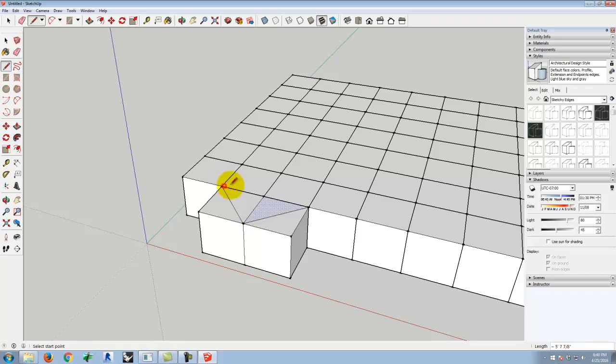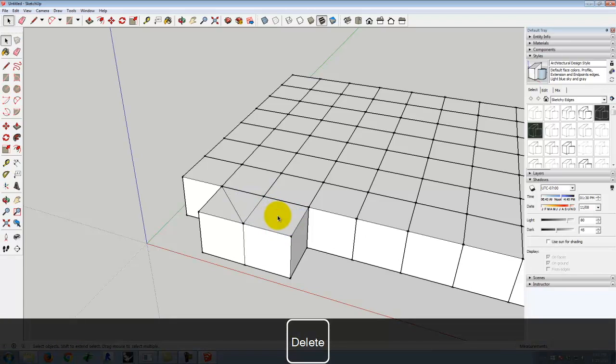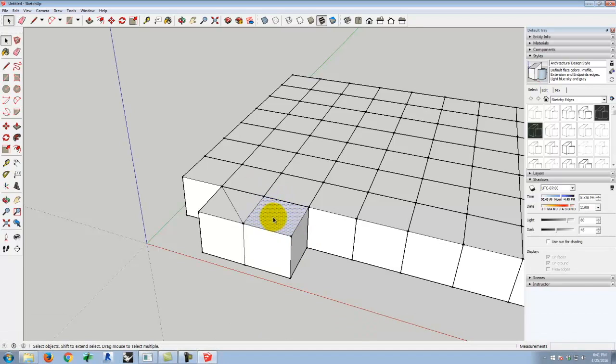And one of the ways that SketchUp works is whenever you draw a line through a surface, it will split the surface into 2 pieces. If I were to delete that line, it would let my surface go back to just one surface. So there isn't really a trim function in the world of SketchUp. You just divide something by another line, and then you can delete it. So anytime there's an intersection.